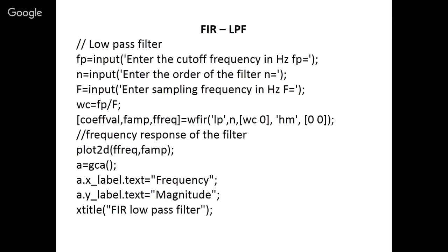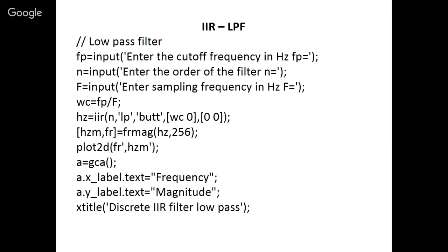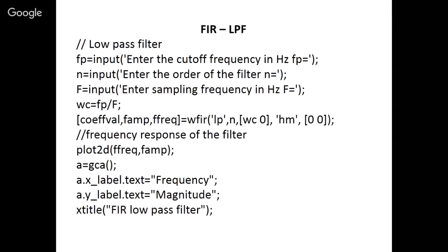And for the filter design in SCILAB programming, we have used this WFIR. This is the window FIR filter. That means by the name only you can understand that this FIR filter has been designed by the window technique. So in this WFIR command, there are options.